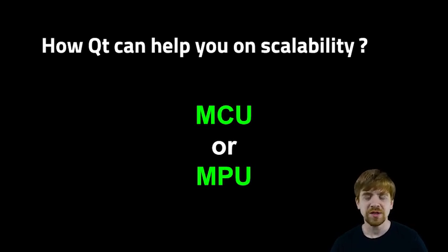The big advantage of an MCU also is the easy setup behind it, because it runs directly on bare metal, so no operating system to set up, or FreeRTOS, which is a lightweight OS that is quite easy to define. Also, you need to consider the number of animations you put in your applications and things like this. But if your application is quite simple on a small screen, you may consider a microcontroller for your UI. But it's not this one that I would like to cover more here.